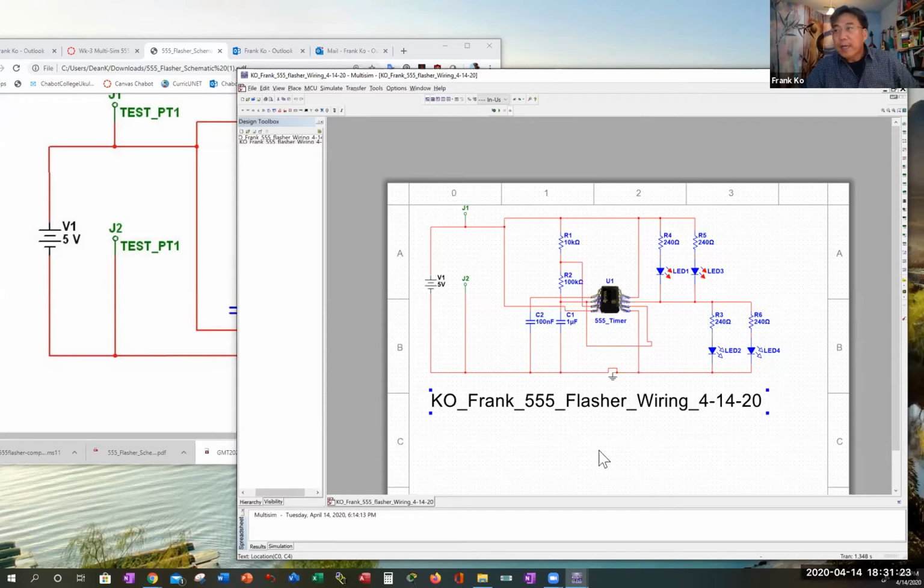this exercise. It doesn't take very long, but now it's saved, and it's got to be saved with the 1 microfarad capacitor. Yes, it starts with the 10, but you've got to change it to 1, because if you turn this in, and I'm looking at your file, and these LEDs are not switching this fast, and you're forcing me to wait 8 seconds between switches, that's half score, people. Can you imagine if everybody turned in this document? I'm waiting 8 to 10 seconds, and finally the LEDs flash. That's insane. Is everybody clear what the assignment is in Multisim?